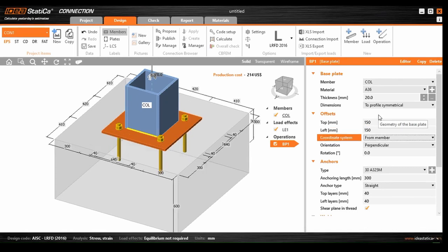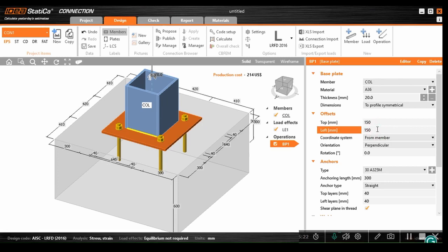So my column is 340 millimeter long in both directions. It is a square. We added 150 millimeter from each edge of the column, so 340 plus 2 times 150 equals 640 millimeter or 64 centimeter. It's a quick description to why I added 150 here and here.